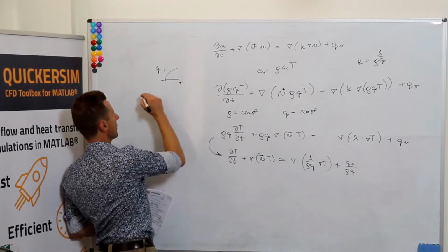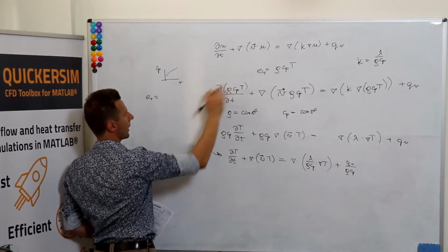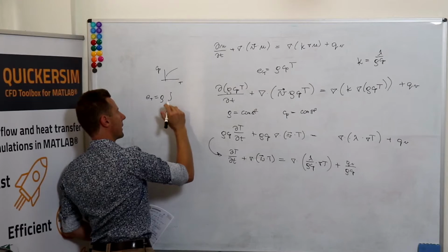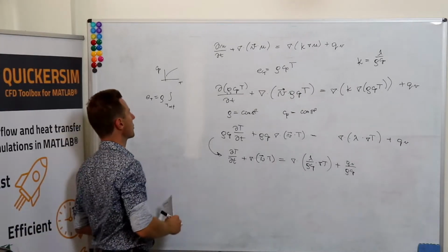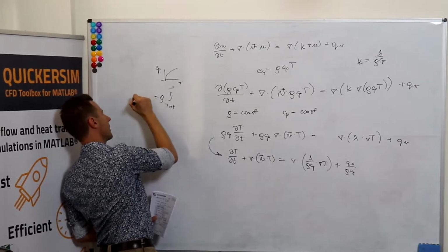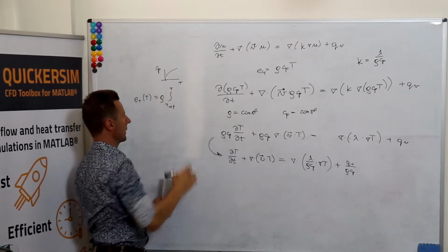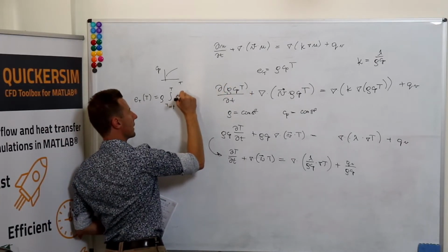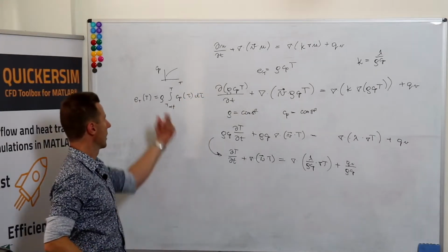And the proper definition of the thermal energy is nothing else than, if we multiply it already by density, then it should be like taking the integral from some reference temperature, whatever the reference temperature is, we can define it, up to the thermal energy at temperature T. Then we need to integrate up to T, taking the Cp function that depends on temperature, and we're integrating over the temperature.